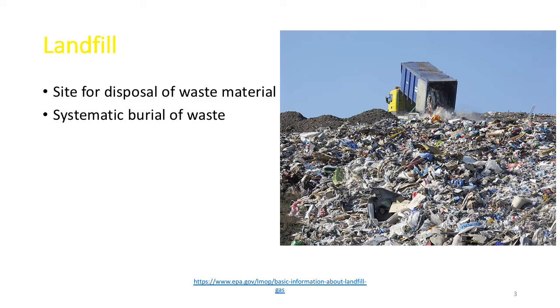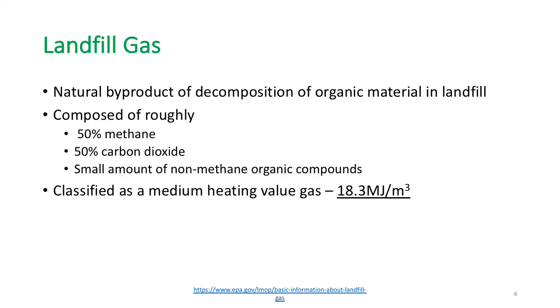So, starting with what is landfill? When waste is disposed at a particular site and it is buried in a systematic way, it is known as landfill. So, now moving on to landfill gas. It is a natural byproduct of decomposition of the organic material in the landfill. It is composed of 50% methane, 50% carbon dioxide, and small amount of non-methane organic compounds. It is also classified as medium heating value gas, which is 18.3 megajoule per cubic meter.